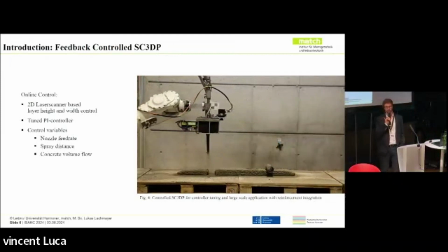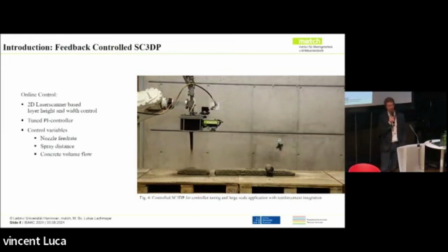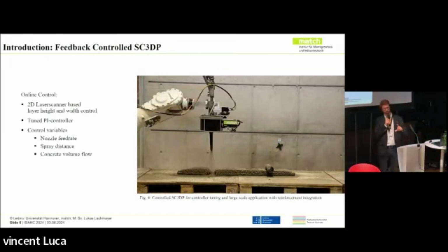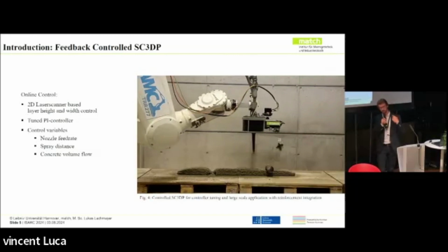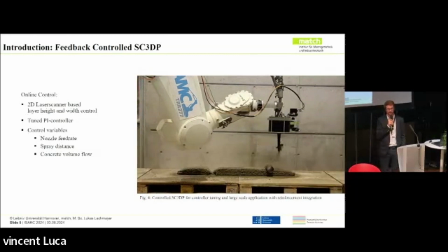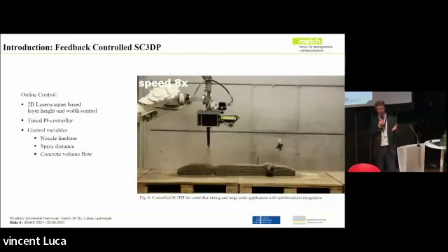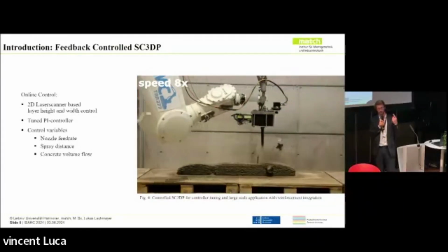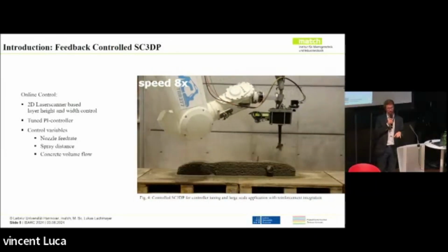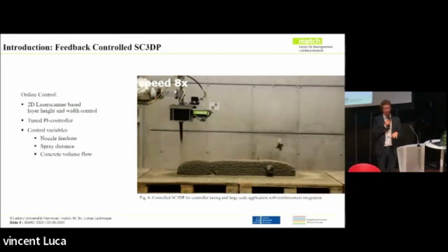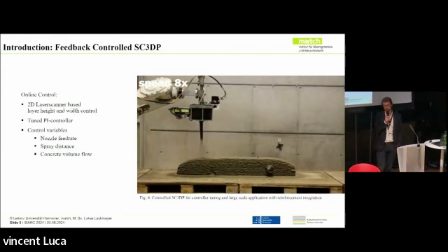We have those control algorithms, and they work based on evaluating the distance from the scanner to the concrete. As soon as we insert short rebars, this data gets corrupted. So I need to exclude the rebar from these control algorithms. However, this can't be done based on the laser scanner data because I can't differentiate between what is concrete and what is rebar or reinforcement. So I use this system and this algorithm to get the information on what I'm currently sensing with the laser scanner. Is it reinforcement or is it concrete? To stabilize these control algorithms, that's my use case currently.